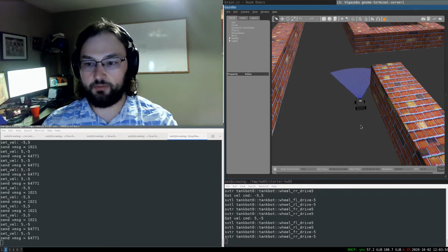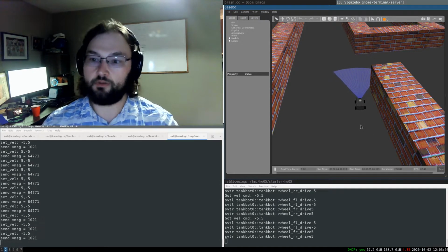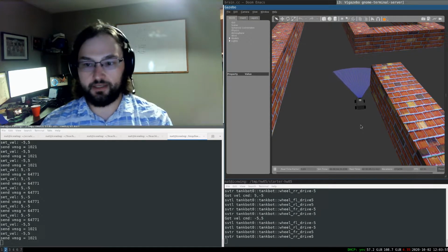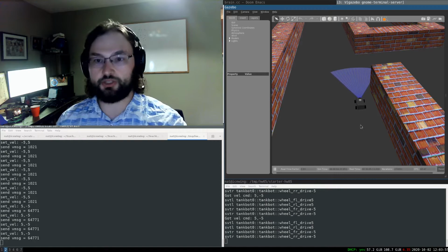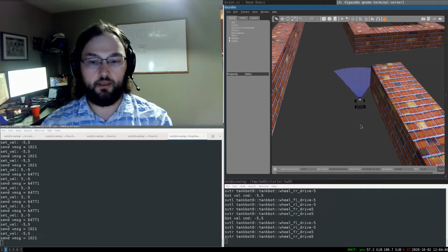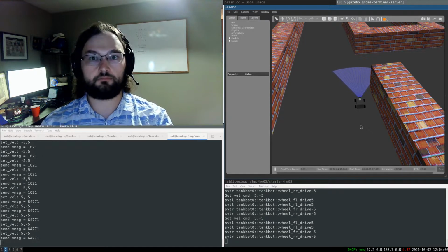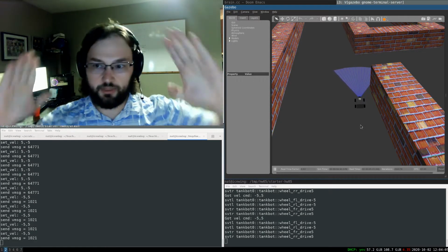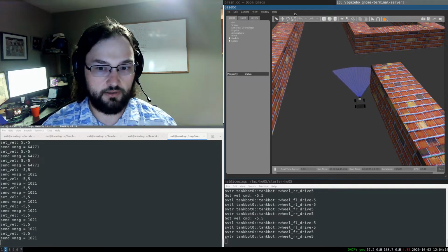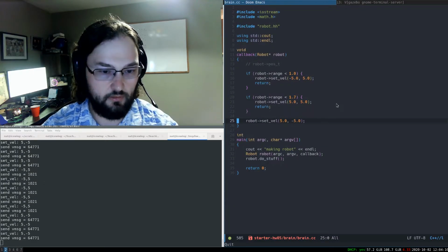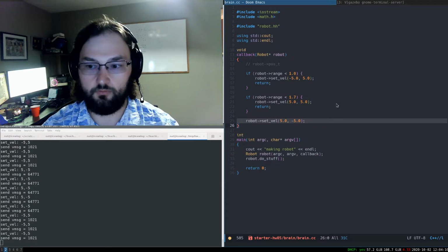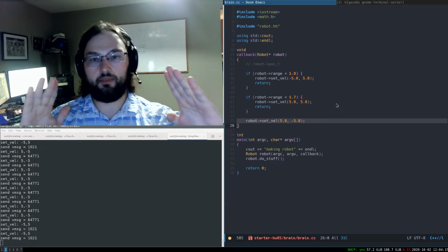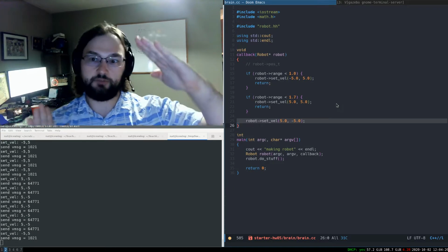In practice, the simulation physics are awful. It's not that Gazebo is especially awful, it's just that the robot that I built is bad. The actual behavior is that we can reliably turn in place if we set the velocity of one side to a speed, and the other side to exactly the same speed negative.